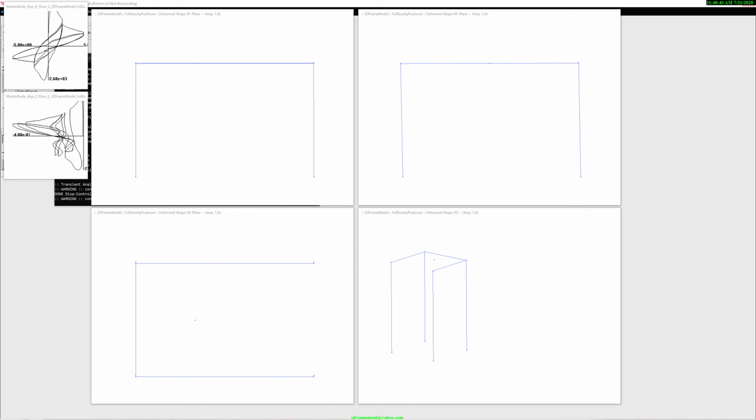Interesting to see what the response is in the Z direction. If you look at these deformations, you see this dot here. This node here is because we have a rigid diaphragm definition. This is the master node that I am plotting and controlling for the pushover analysis. And the program itself does everything you need for rigid diaphragms. Right now it just does it for the floor, so it's pretty straightforward and easy to define.